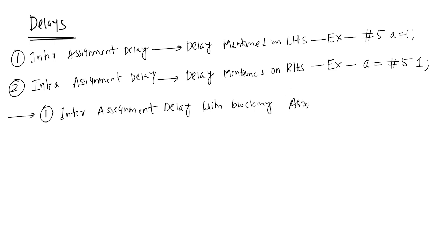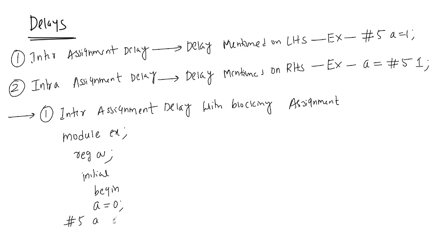Suppose we take one example: module example, using reg a, initial begin, a = 0; #5 a = 1; #10 a = 0; end, endmodule.